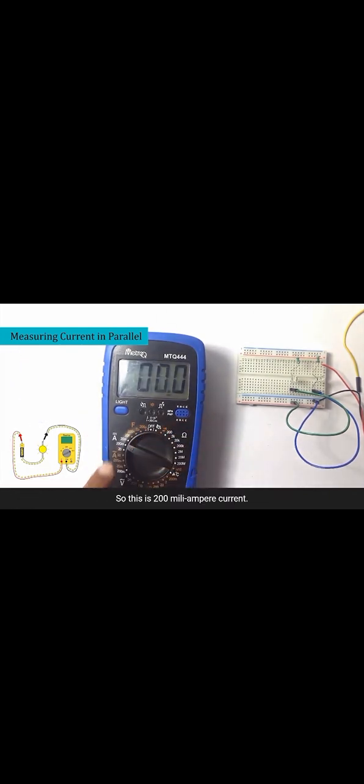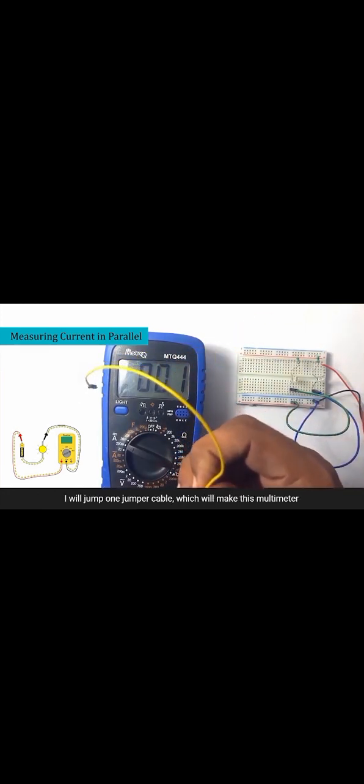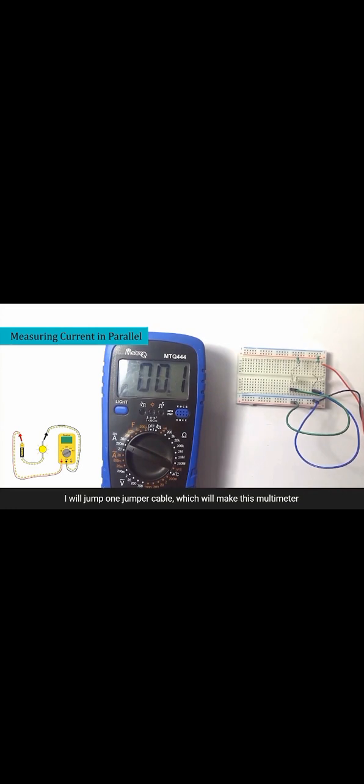So this is 200 milliampere current, where it can measure up to 200 milliamps. I will jump one jumper cable which will make this multimeter in series. I'll connect it here and connect this jumper cable to the positive terminal.